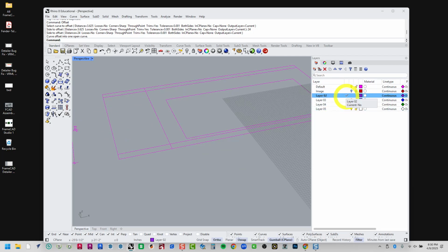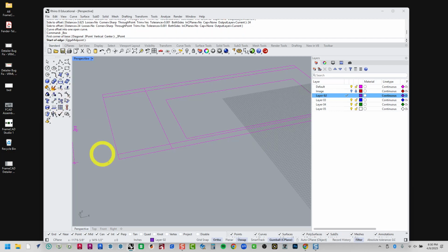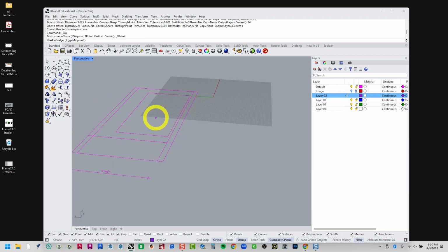All right, I'm going to use this little 2D drawing that I've got set up, right? It's the full maximum capacity of the trailer itself. It's also got 3 5/8 inch walls on 2 of the sides. So maybe I go to the interior dimensions here, and this one here for my second point. For my third point, maybe I want to do 24 inches. Hit enter, click once, right?